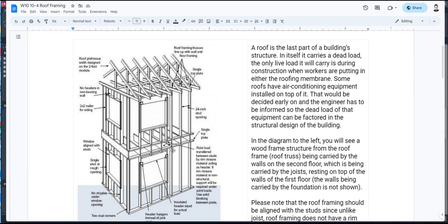And your joist would be covered by a rim closure or a rim joist. On top of that rim joist, you're going to have your floor, which are basically just sheetings of plywood. It doesn't show it here too. And then on the joist on plywood, you would have your second floor wall, and just like the first floor, they will be spaced according to whatever the engineer would say. This one is 24 inches, and according to some jurisdictions, the maximum is 16 inches. In this case, it's 24 inches in some jurisdictions, but I think California, the maximum is 16.